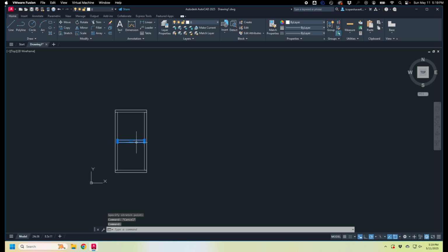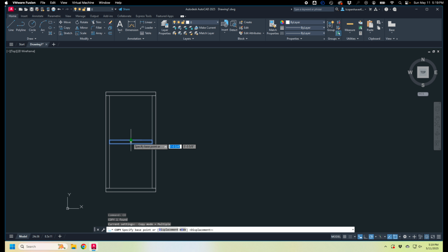And then I'm going to copy it again. And this time, I know that I want one 24 inches above and 24 inches below, because I'm going to do every 2 inches on center. This is a 4x8. So I can just type in 24 spacebar, 24 spacebar. So I basically used all of the stuff that I had already, some fairly simple commands to give myself a drawing that is actually going to be useful later, which is kind of lovely.